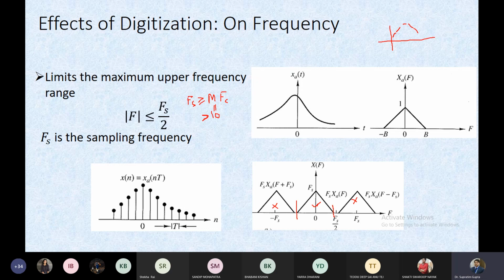All right. Now, how to decide that band limitation, the band? For example, our speech signal, the voice. Whatever we speak has a maximum of 4 kilohertz of band. So the 0 to 4 kilohertz band is fixed for that. Beyond that, it is not meaningful for any information. So we can use at least an 8 kilohertz frequency to sample that.